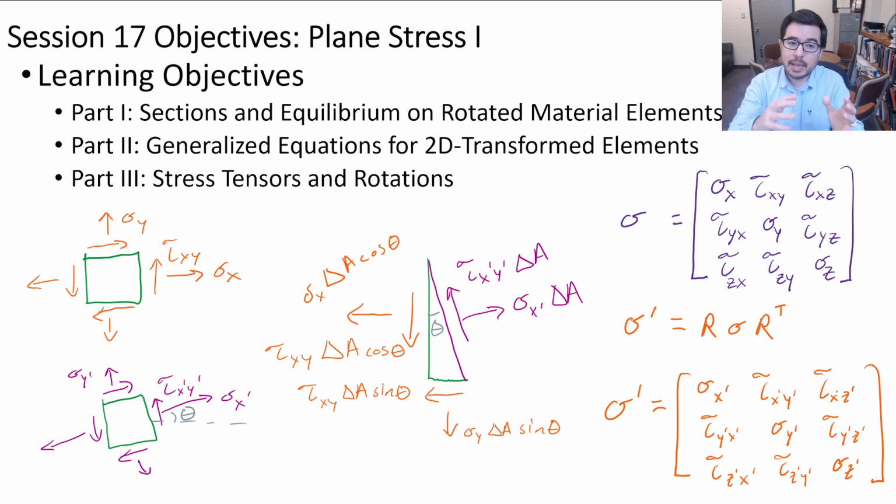And by understanding these relationships between normal stresses and shear stresses as we perform transformations, we can get to a state, or better said, an orientation where we have maximum values for shear stresses or maximum values for normal stresses, and then be able to link these calculations to whether or not a material might fail. Okay, so let's go back before we get into all this